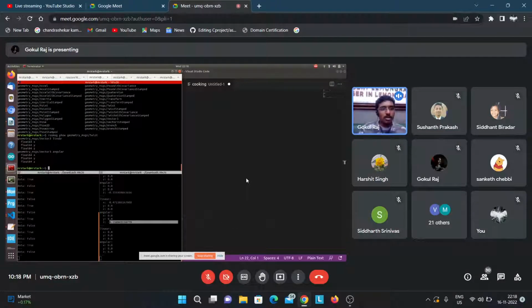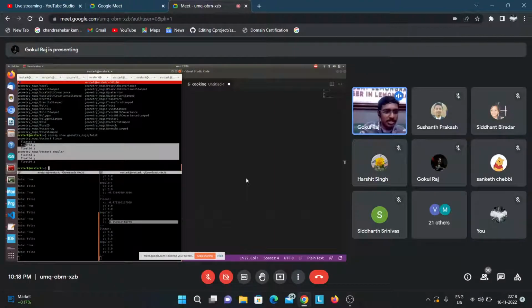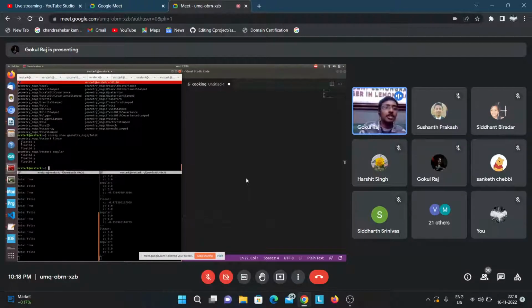Okay, cool. So now, let's say you want to make an actual robot follow a line, and you want to pass commands using ROS. Instead of publishing PWM values, you can just publish this twist message, and on the Arduino side you can subscribe to this twist message and get the PWM based on the calculation with X and Z, and you can move your robot.